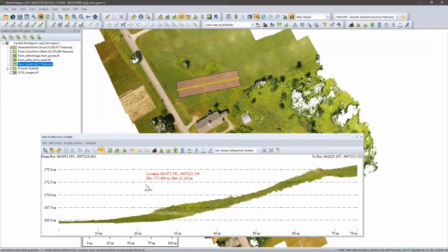Kind of backing up a little bit, a question came in about the procedure and maybe the planning process. How much overlap do we typically recommend if you're trying to achieve what was achieved here? Yeah, absolutely. The optimal overlap that we recommend is definitely about 60%. The minimum requirement is more like a 40% overlap. But when you are doing your flight planning, there's one planned overlap, and then there's the actual overlap that you get based on whatever happens to your drone while it's in the air. So we definitely recommend shooting for 60% overlap.